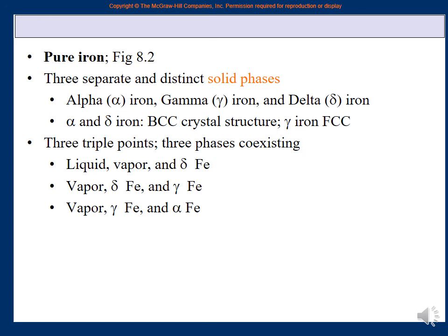And it is because of this particular thing that iron has three solid phases. So if you can play around while cooling iron, so that it does not go to this phase, it goes to the other one. It does not go to this phase, it goes to the third one. So it is the same material. By controlling how you cool it after melting it, you can control the properties.